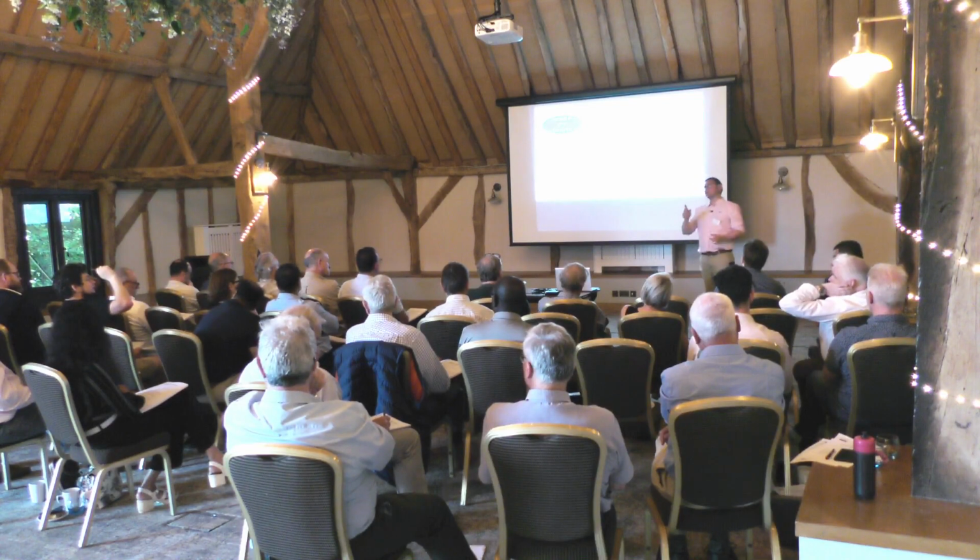Now, there's a bit more. Yes? Is it similar to this one? Well, let's use this as an example. Relating to B3, it becomes much, much more complicated when you have complex roof structures, such as this. Because if it's contributing to the stability of another element, a wall for example, or a compartment, that roof structure would need to be fire resistant, particularly if you have roof members that are passing through a compartment, which does happen particularly with older buildings.